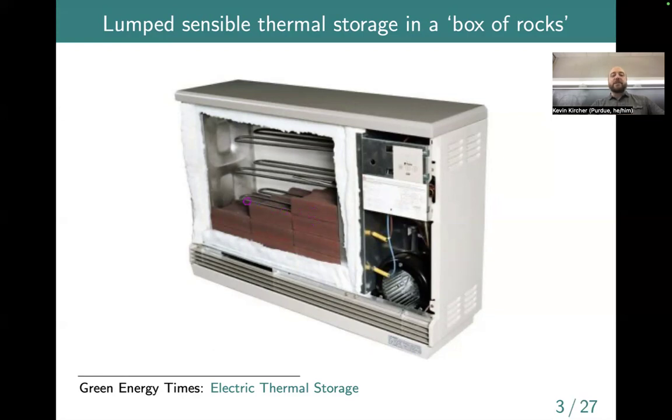So when you want to store energy in here, you run current through these heating elements. You get I squared R joule heating losses from there, and they basically heat up the bricks. And then when you want to discharge the thermal energy storage, there's a blower. This thing is basically a fan that would suck in air, blow it through the insulated chamber, and then you would get hot air coming out the bottom of the device. So very simple. This is actually kind of cool because although you would lose energy through the wall, it's not perfectly insulated.